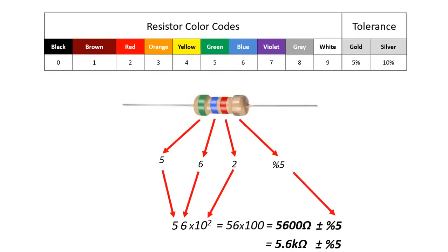Any resistor of over 1,000 ohms is typically shortened using the letter K. For instance, 1,000 would be 1 kiloohm, 3,900 ohms would be translated to 3.9 kiloohms, and 470,000 ohms would become 470 kiloohms. Values of ohms over a million are represented using the letter M. In this case, 1 million ohms would become 1 megohm.